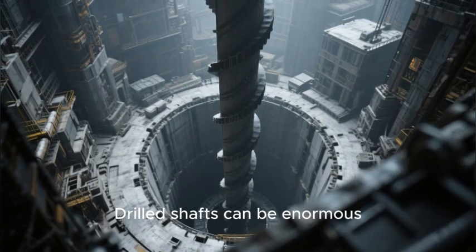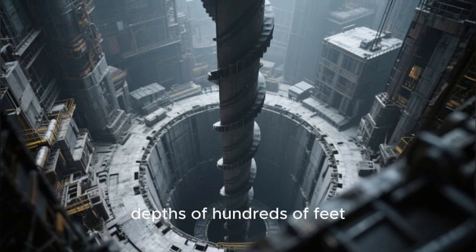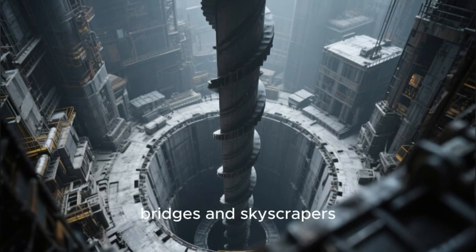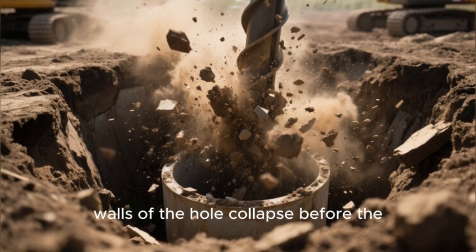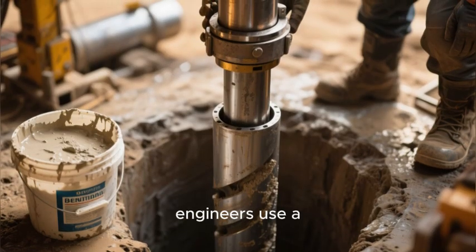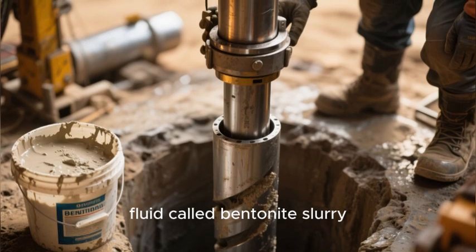Drilled shafts can be enormous, reaching diameters of 10 feet or more and depths of hundreds of feet, making them the foundation of choice for massive bridges and skyscrapers. A critical on-site risk with drilled shafts is caving, where the soil walls of the hole collapse before the concrete is poured. To prevent this, engineers use a temporary steel casing or a stabilizing drilling fluid called bentonite slurry.